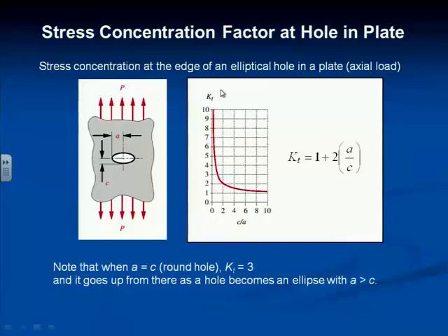There have been some theoretical studies done for certain neat geometries. A hole in a plate. You can actually calculate with closed form equations what the stress concentration will be if you have a hole in what they refer to as a semi-infinite plate. All that means is there's a little hole and a lot of plate, so that away from the hole nothing's happening that's affected by the hole.